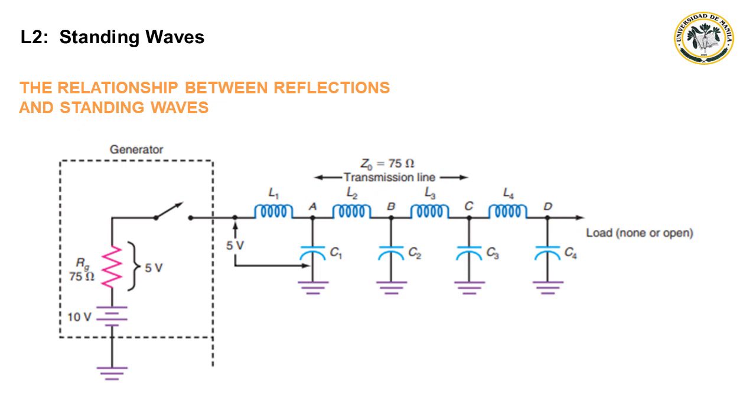The preceding description concerned what is known as an open circuit load. Another extreme condition is a short circuit load. Open and shorted transmission lines are sometimes used to create special effects. In practice, however, the load on a transmission line is neither infinite nor zero ohm.